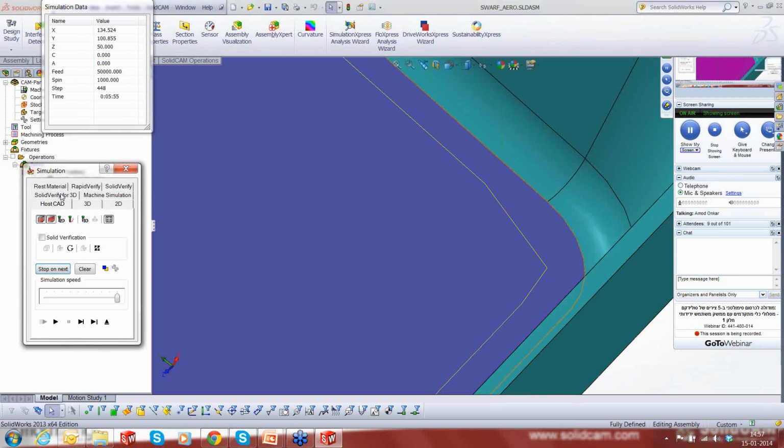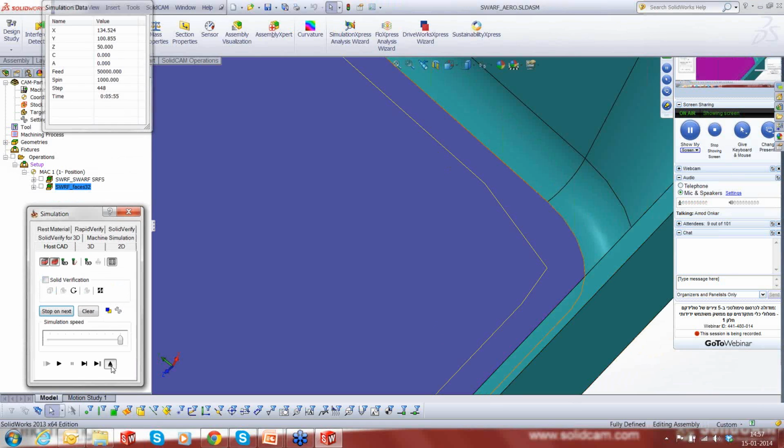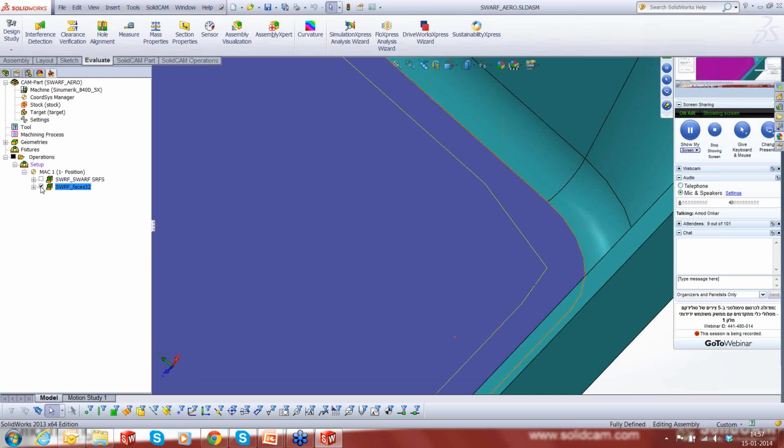Let me open up the toolpath. Okay, you can see that it should have ideally moved around this fillet, but I see a very sharp corner out here. We have to now find why this is happening, and in a moment we'll find out why that is happening.